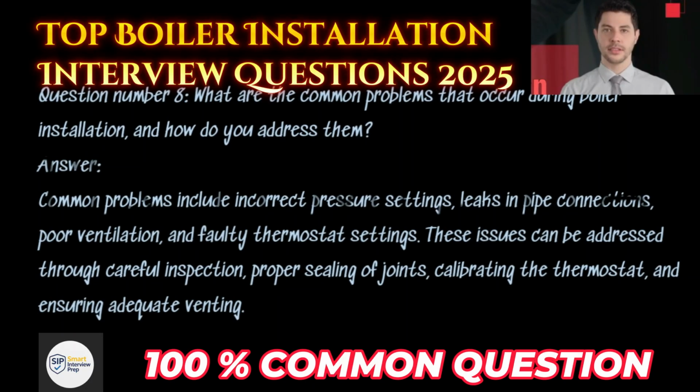Question number 8. What are the common problems that occur during boiler installation, and how do you address them? Answer. Common problems include incorrect pressure settings, leaks in pipe connections, poor ventilation, and faulty thermostat settings. These issues can be addressed through careful inspection, proper sealing of joints, calibrating the thermostat, and ensuring adequate venting.